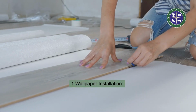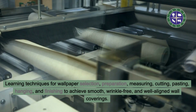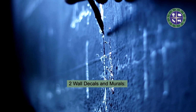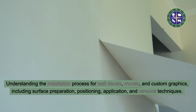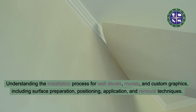1. Wallpaper installation. Learning techniques for wallpaper selection, preparation, measuring, cutting, pasting, hanging, and finishing to achieve smooth, wrinkle-free, and well-aligned wall coverings. 2. Wall decals and murals. Understanding the installation process for wall decals, murals, and custom graphics, including surface preparation, positioning, application, and removal techniques.